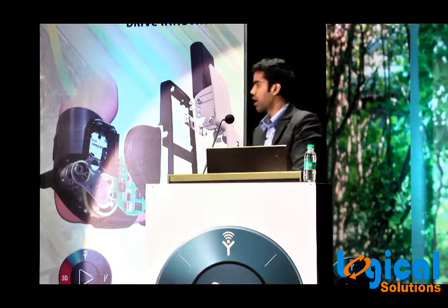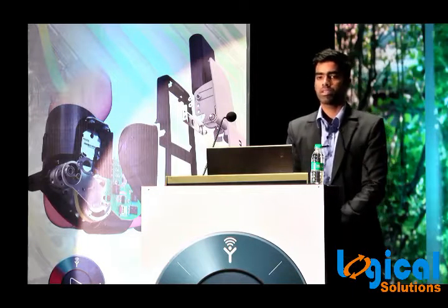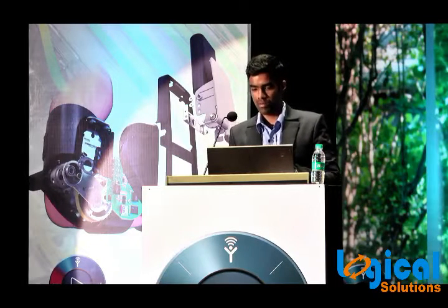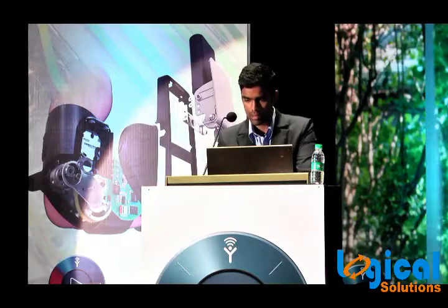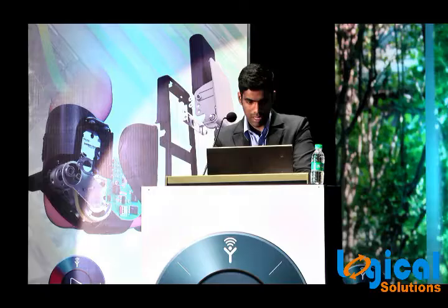Now in this year, we have added planes. So here you can use these planes for mating or for suppressing any of the components. And if you see here in the breadcrumbs itself, we have shown the errors and warnings. So you can click directly here, edit the feature, and add the missing plane. That will be at your fingertips, right? So just by clicking a reference, you can add a mate. I'm going to add a coincident mate directly.